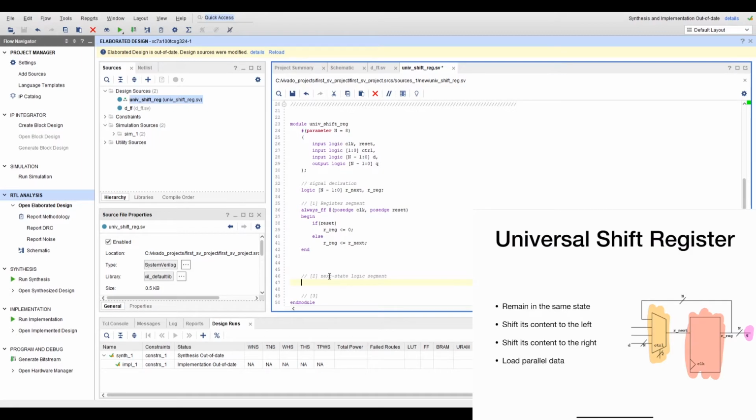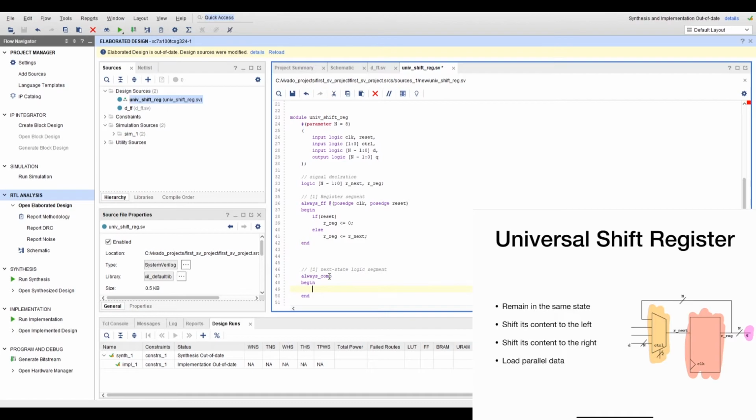For example, you can instantiate some sort of a 4x1 multiplexer, the one we built previously, and just use it. But what I'm going to do is describe it behaviorally using an always combinational block. It's a combinational circuit, so you can use always_comb, not always_ff. Okay, so that's good. Since it's a multiplexer, it's basically routing.